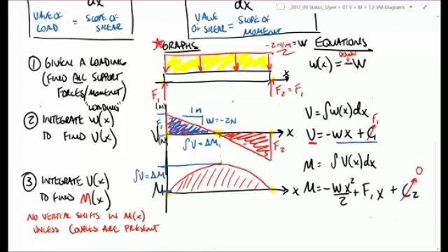Your book actually uses a technique similar to 7.1, where you take slices of this and solve for an unknown location. You'll say that this is some value of x over to some unknown cut point, and you write those shear, moment, and axial load equations just like you did in 7.1, but instead of being absolute, they're due to this unknown distance x.